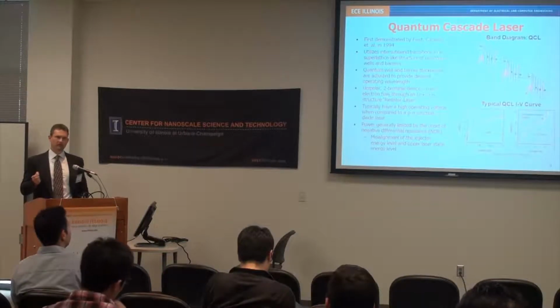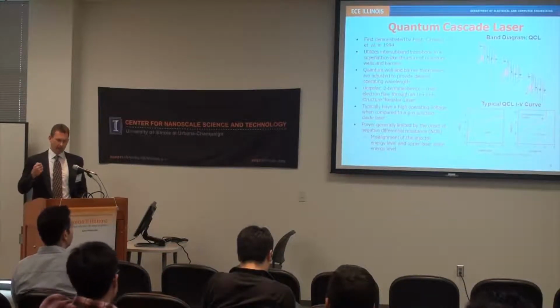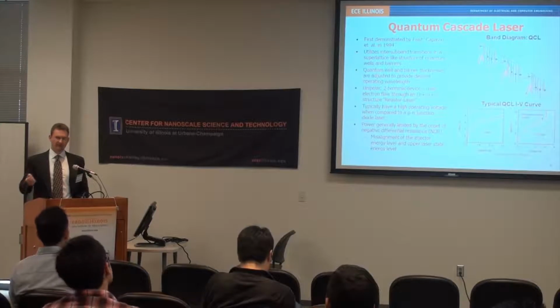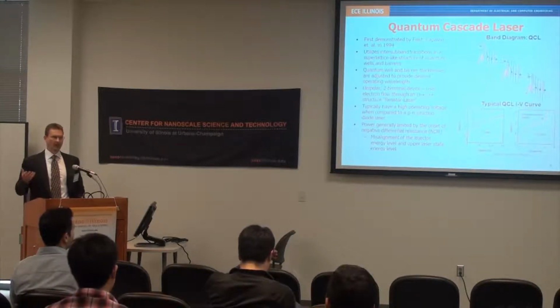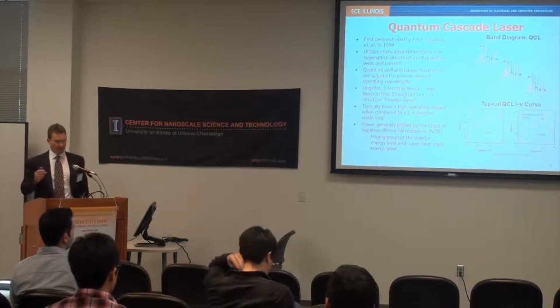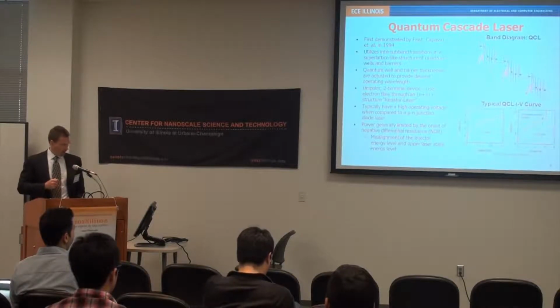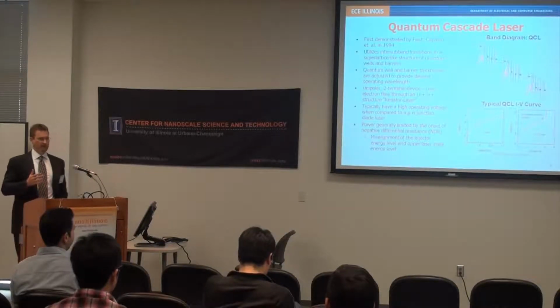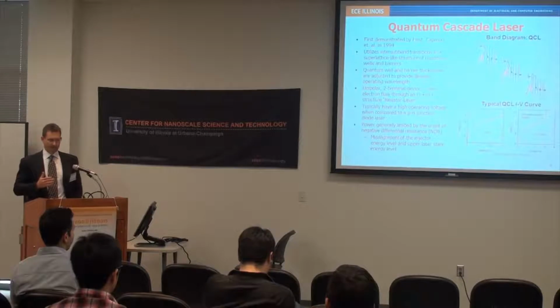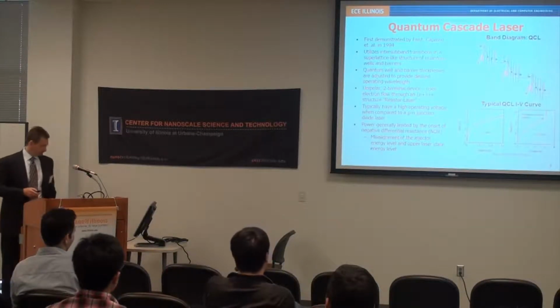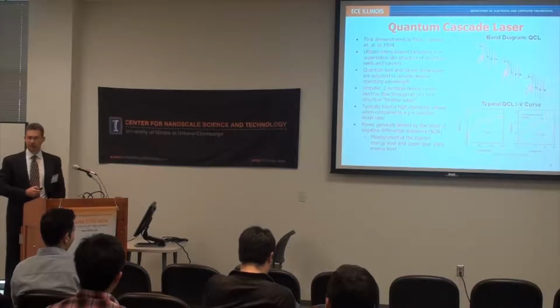So we're effectively changing the fundamental characteristics of the device, the state lifetimes and the transition energies, as we change the bias on this device itself. It's an N+IN device. So from a semiconductor laser person's perspective, and some people cringe when I say this, it's a resistor laser. But still a very interesting resistor laser.